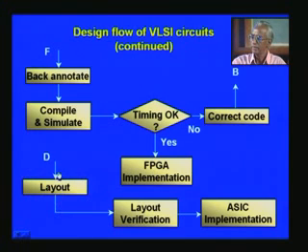Another alternative is that the Synopsys DC compiler itself will give you, with your own constraints, some TCL files, etc., a database file. You can feed that database file straight away to the ASIC vendor, and then he'll take care of layout as well as layout verification, and he may finally give you back the connected thing, because we don't have that right here, and many people may not have this.